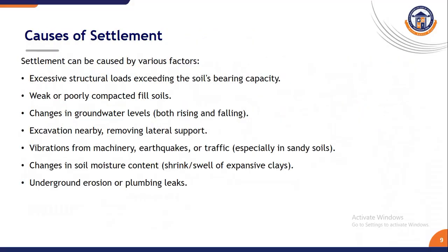The next topic is causes of settlement. Various categories are there. Excessive structural loads exceeding the soil bearing capacity. After that, settlement may occur due to weak or poorly compacted soil, change in groundwater level, nearby excavation, and vibration. Various causes are there for settlement of a building. A small example is lowering of the groundwater table near a building, which can increase effective stress in clay, leading to additional settlement.